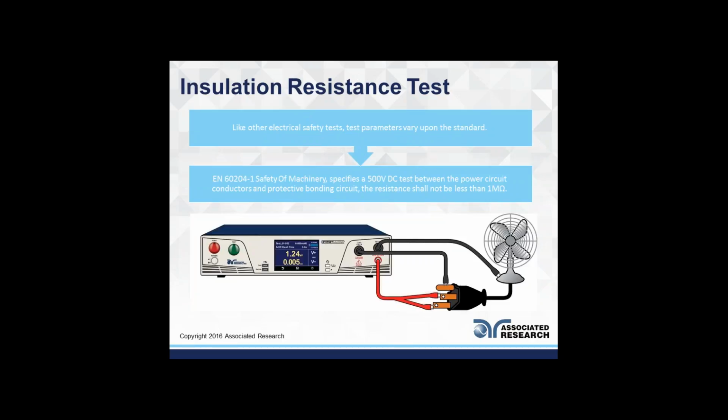Quick look at how the insulation resistance test will be performed. Again, the test is the same test, but in the results we're getting the actual ohmic resistance value of your insulation. Earlier we were getting the leakage value, which was the current leaking through the insulation. Now we're getting the actual resistance value of your insulation. And it's not performed at the high voltages we mentioned earlier. It's usually performed at low voltage, either 500 volts or 1,000 volts.